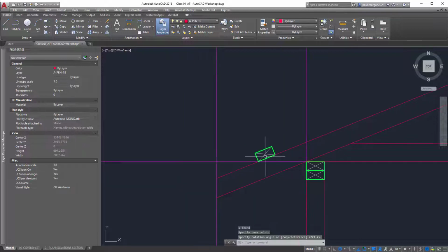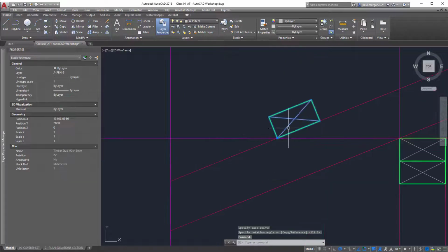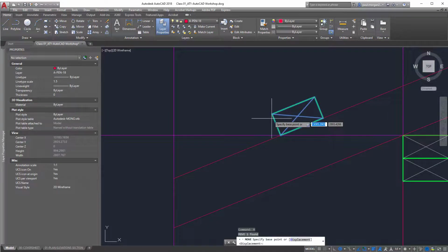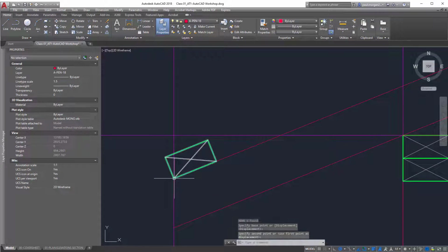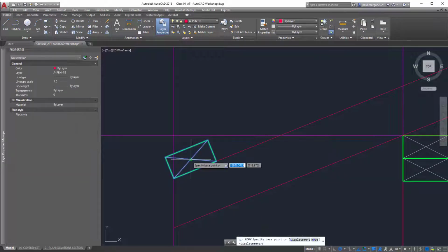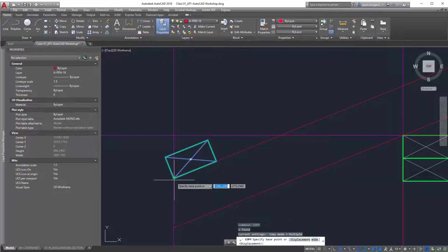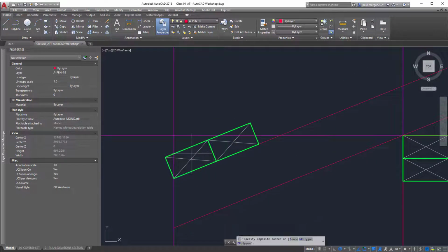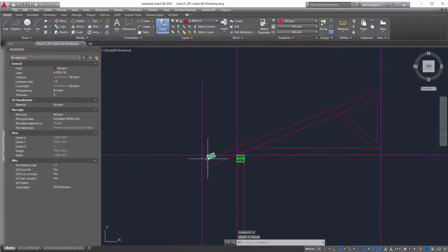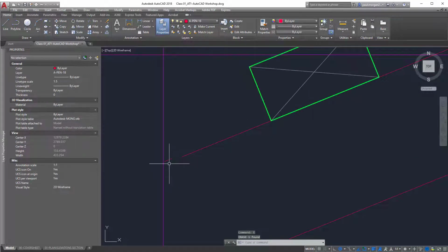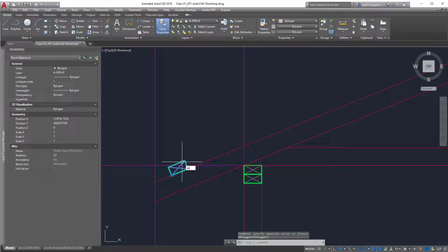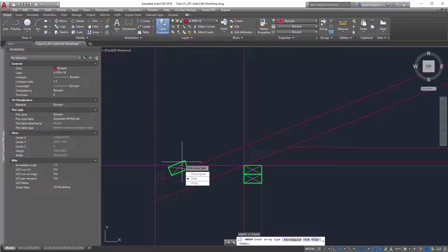So that's very helpful. I'll then take this stud, and what I'm going to do is I'm going to move this all the way to the base of the truss, back to here, and then I'm going to move this up, basically 90 mil, like one truss length. Okay, so we're starting 90 mil from the edge of the truss. I'm then going to use the command called array, and it's going to give us three options.